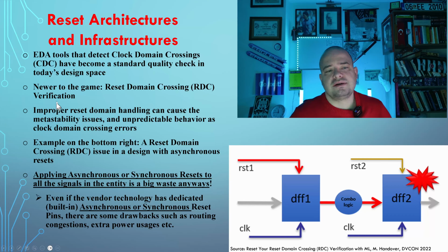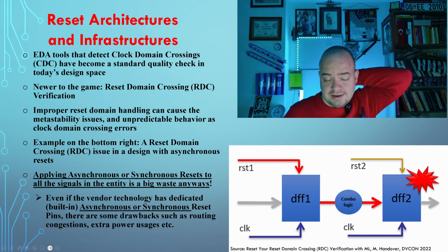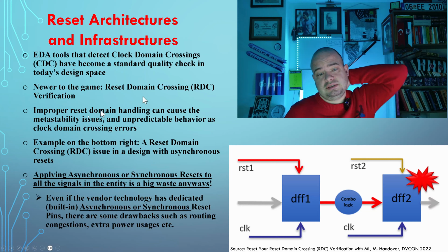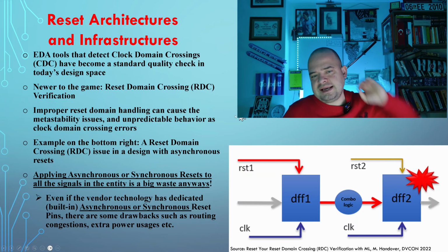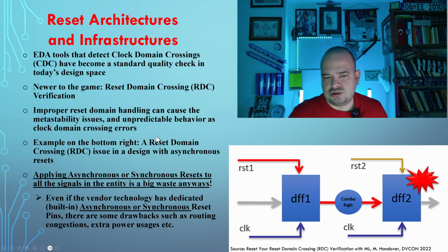But newer to this game, RDC tools, reset domain crossing verification, are also now on the field. So improper reset domain handling can cause metastability issues and unpredictable behavior, as clock domain crossing errors do. As an example on the bottom right, a reset domain crossing RDC issue in a design with asynchronous resets.